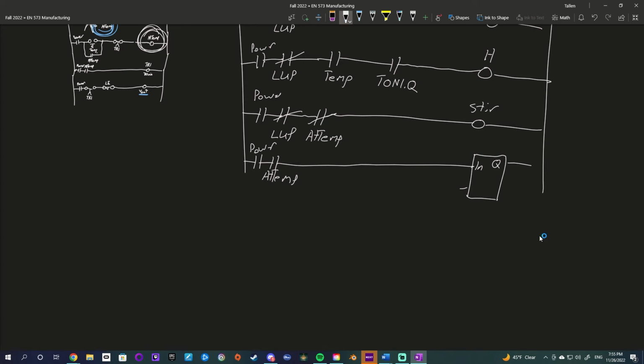There is also, what is it? I think PT and ET. ET is the elapsed time that has gone by since it received the signal. PT is whatever time you're looking for. So to input the amount that you want your delay to be, and this is our TON1.Q, by the way,